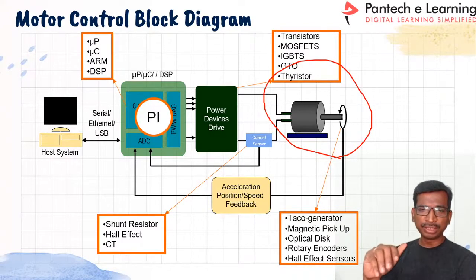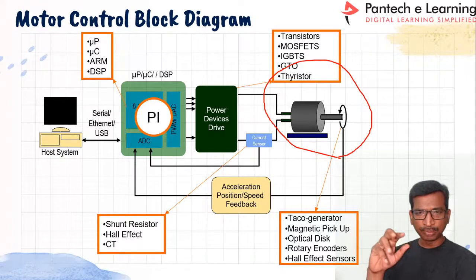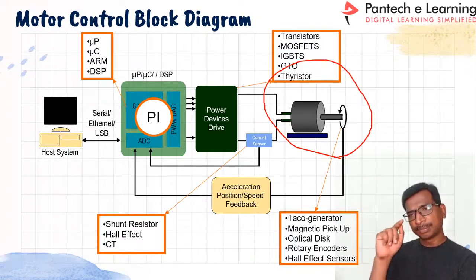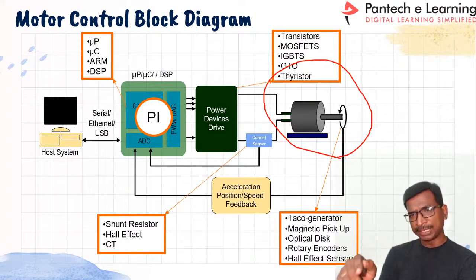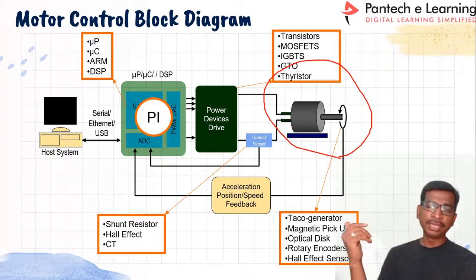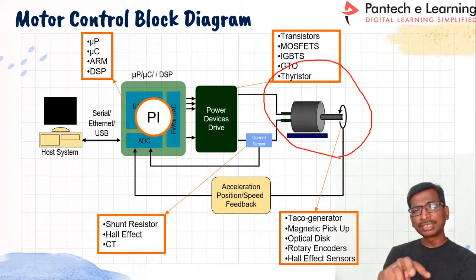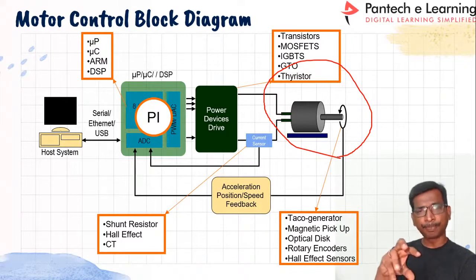Here, one thing we have to keep in mind: whatever sensors we place at the measured point on the plant, that sensor value is going to be connected to the microcontroller, right? So if any fault occurs on the plant, that fault should not carry over to the microcontroller, because the microcontroller is the heart of the entire plant.